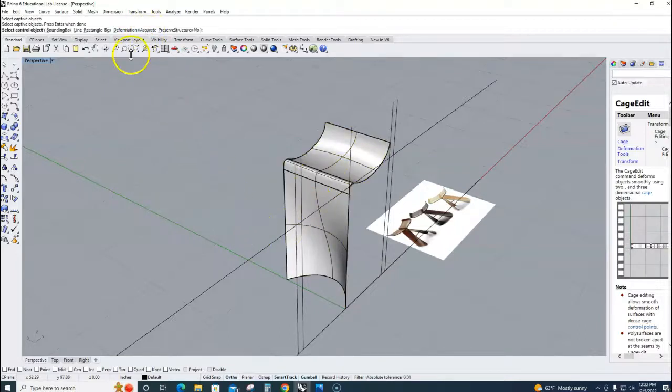So we're going to click that, and we're going to click bounding box, and for the coordinate system, we're going to take the default world, and then it asks how many points, right? So I basically want 5, 5, and 5.